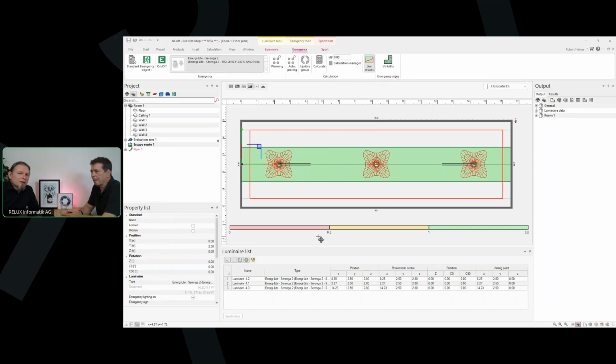Or at least you need to be aware of the LDC, so the LDC can cover more width and not just the middle line. Some really specific luminaires for hallways, which can reach up to 30 meters, are really focused on the middle line. And these luminaires may fail if the escape route is too wide and needs more coverage on the outer parts, where we also have the 1 lux minimum requirement.